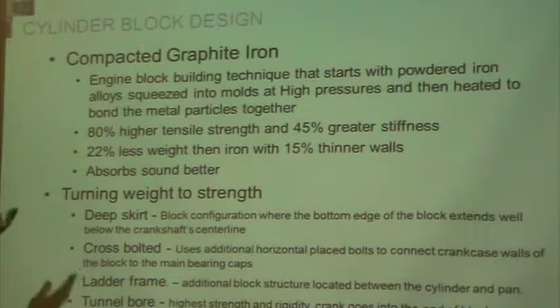They take granular powdered iron, and they mold it, and then they physically press it. We see that with plastic. They'll take plastic BBs and press them together, and it's called sintered. That pressing heats it up and bonds it together, but it's kind of porous, and it allows oil to get into that bearing surface and stay there. So rather than a chrome surface where oil has to be on the surface, in a sintered bearing they can actually put graphite and oils in there, and as it gets hot, it starts drawing them out.